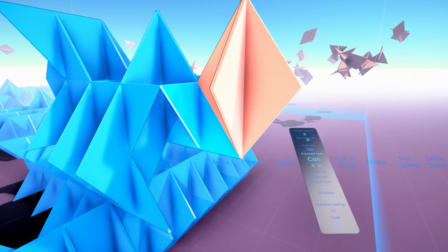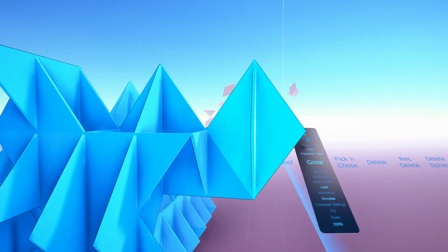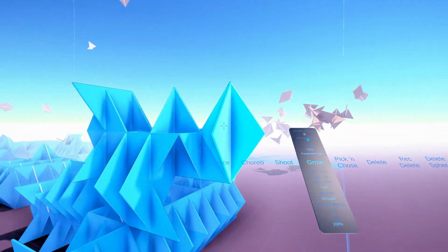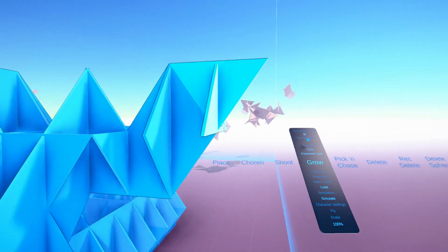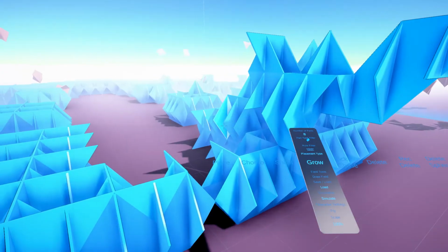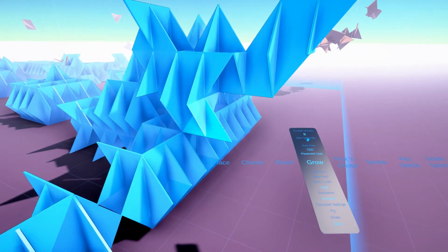And it'll also check for collisions. So you wouldn't be allowed to aggregate a colliding part. And finally, hit enter or return one more time to make the part assemble. And then you could start the process again, add this, and so on. As said, this makes sense for really purposefully aggregating part by part.